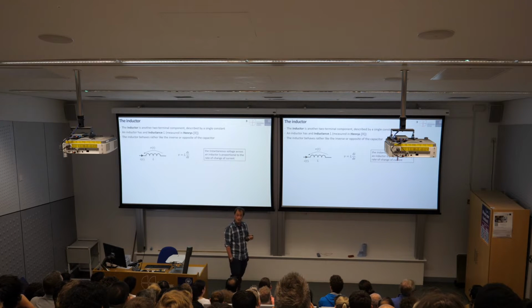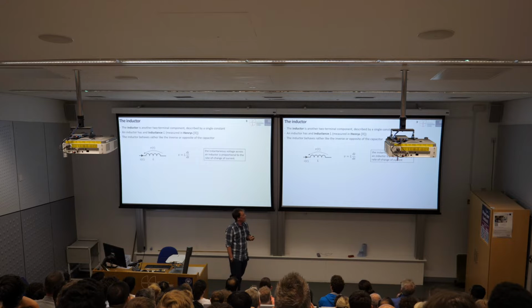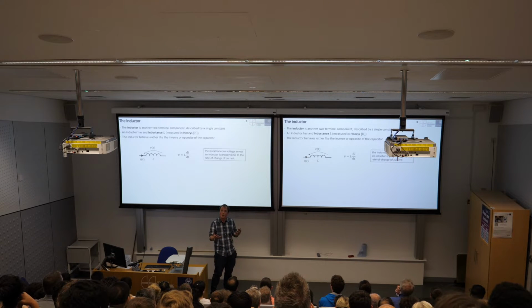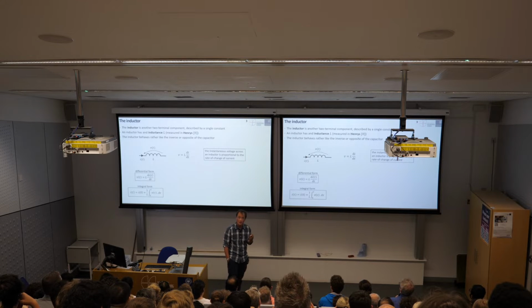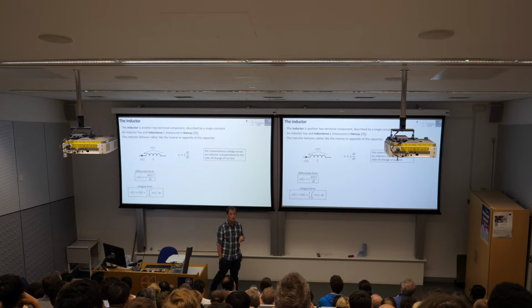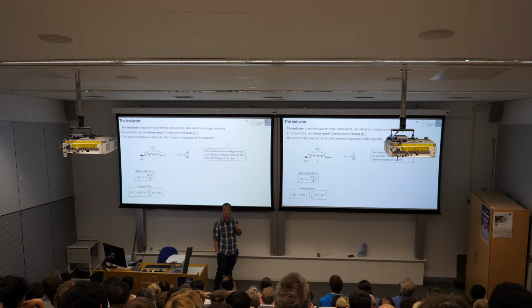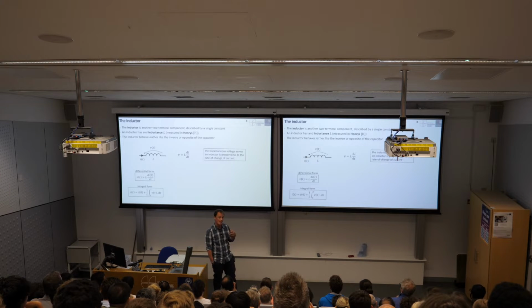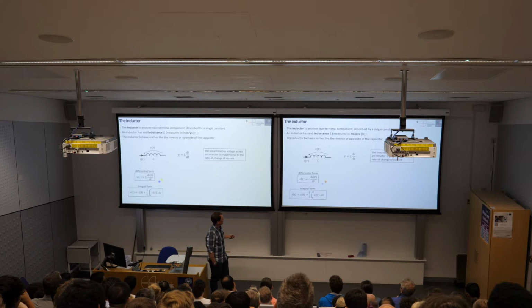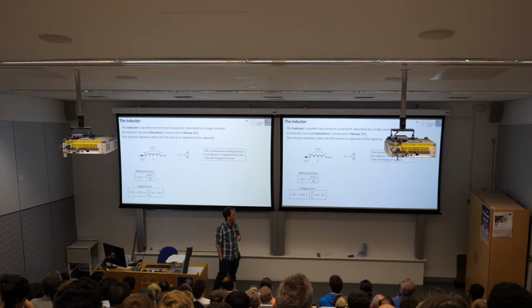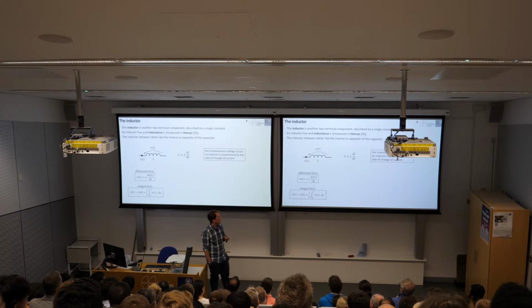Inductance is measured in henries. Nice name, and that completely describes the behavior of an ideal inductor. Of course, if we have a differential equation, we can turn that into an integral by flipping it around, right? So we can say that the current that is flowing at any time t here is equal to some initial current, traditionally we take that at time 0, plus the integral of the voltage applied across that inductor from time 0, at the initial conditions, through to the present time t.